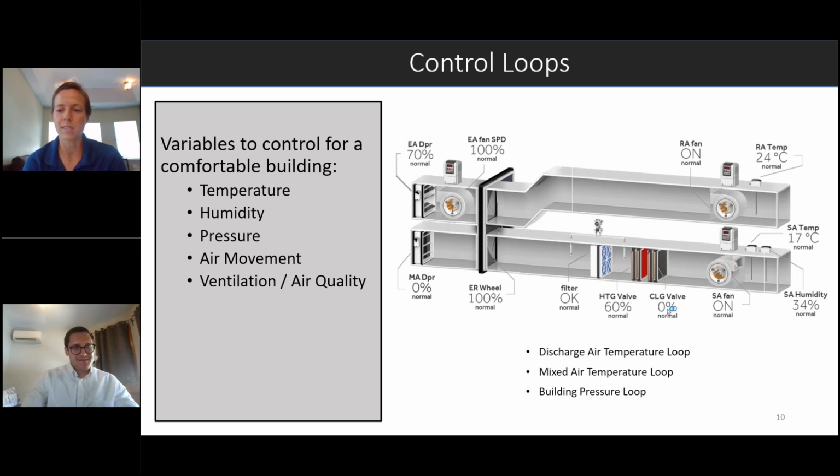What I would say is, I always liked when I was pricing up projects that there was a clean points list, which helped me determine what type of controller to use. If you don't outline all the points you think you'll ultimately use, the controls contractor might price up a smaller fixed point controller.